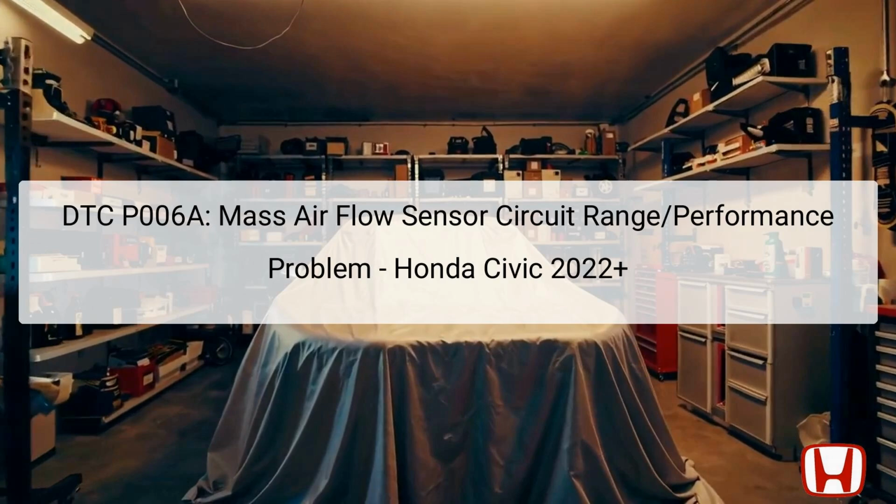The Diagnostic Trouble Code, DTC P006A, indicates a problem with the mass airflow, MAF, sensor circuit, specifically relating to its range or performance characteristics. This DTC arises when there's a discrepancy between the intake air amount measured by the MAF sensor and the amount expected as per the manifold absolute pressure MAP sensor output. The Powertrain Control Module, PCM, which manages the engine's function, flags this anomaly by storing the DTC for further analysis.